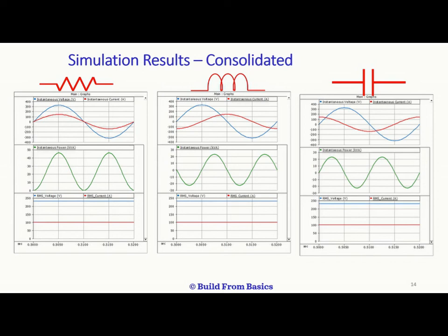That's why it is very important to rate the transformer and AC generator in kVA or MVA or VA, because the current through the transformer winding depends on the load current, right? So it doesn't know whether it's a resistor, inductor or capacitor drawing that current. That's why it is very important to provide the rating in kVA or MVA.